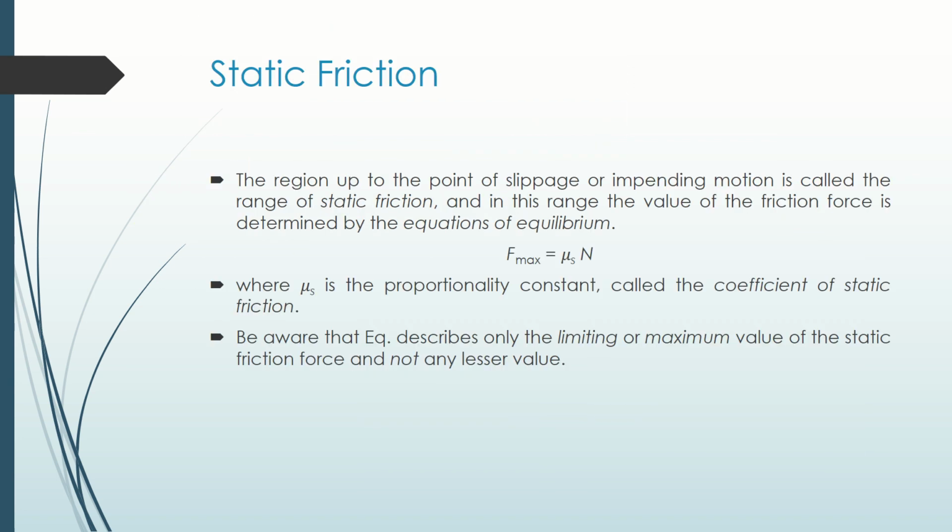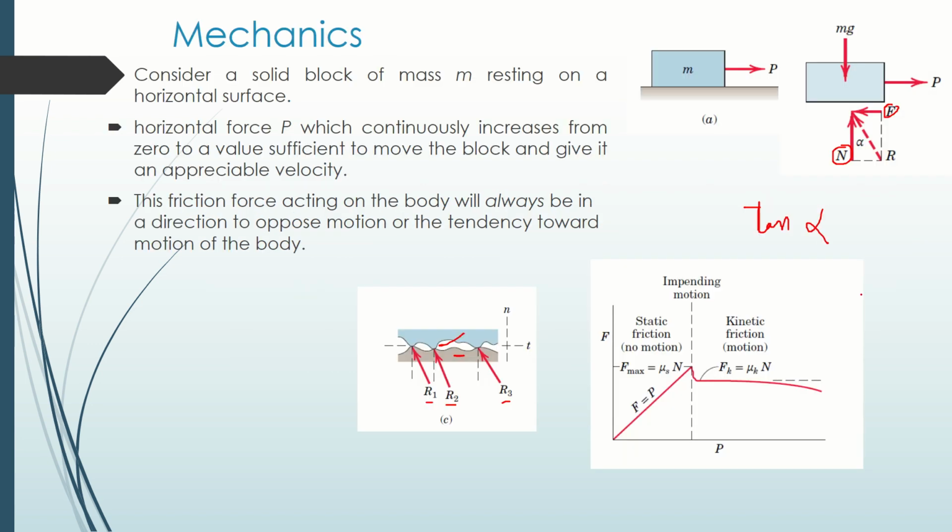Now, we are going to talk about static friction. You have to understand, in this term, the µs is termed as the maximum value. As you can see, you have to cross this value, and this peak is considered µs. Otherwise, the moment you start applying the force, this region does not mean there is friction going on. It can also mean that the mass or the inertial property of the mass is also coming into play.